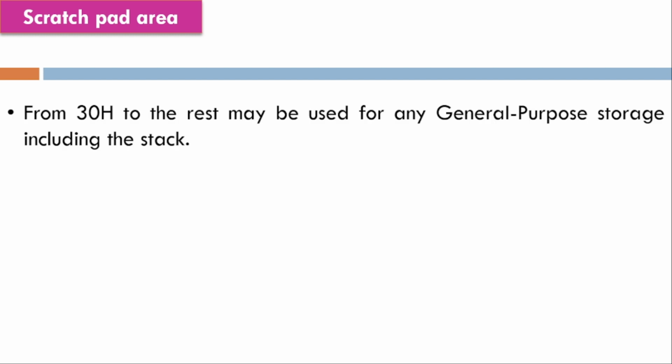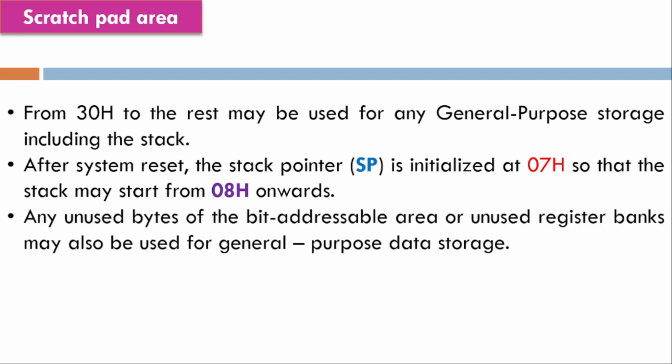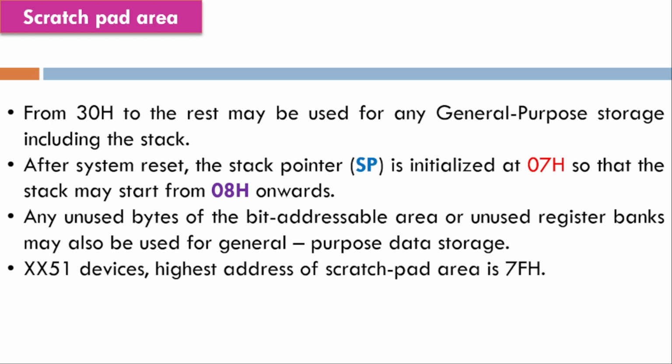From 30 hex onwards, the rest may be used for any general-purpose storage, including the stack. After system reset, the stack pointer, SP, is initialized at 07 hex so that the stack may start from 08H onwards. Any unused bytes of the bit addressable area or unused register banks may also be used for general-purpose data